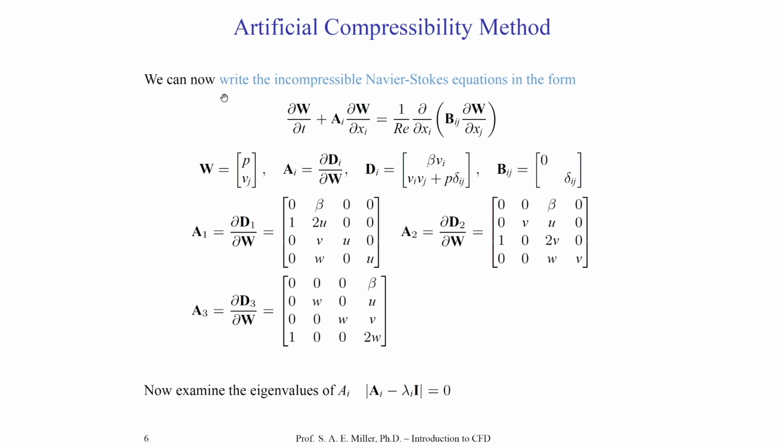In the first equation, we have, of course, our vector form with the definitions of W, A, D, and B. This is all put in, of course, a vector form for pressure and velocity. So, for example, in W, we would have partial P, partial T, and partial Vj, partial T, right there. The coefficients of A and B are written down here along with their particular derivatives. So you've noticed that these coefficients are generally known at one particular space and time in the CFD solution.